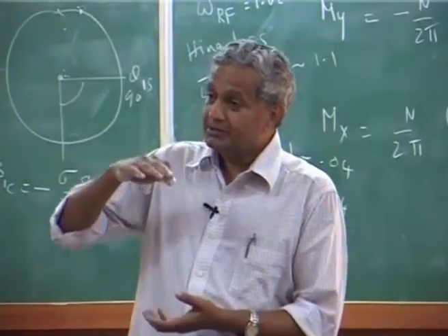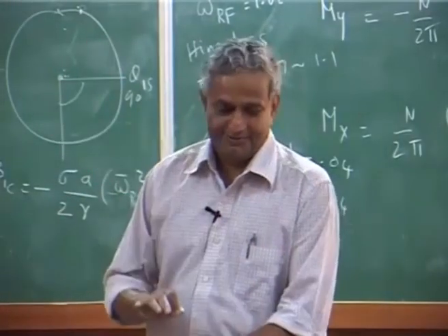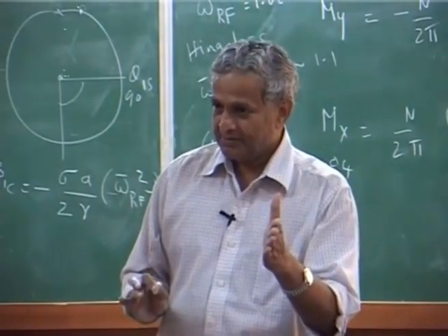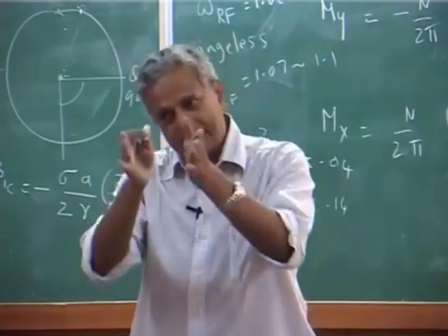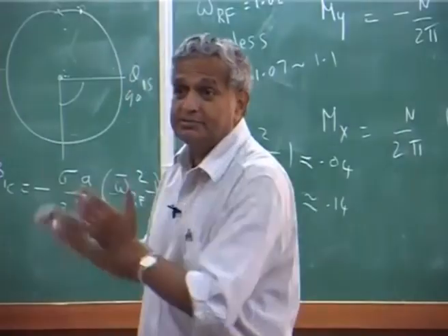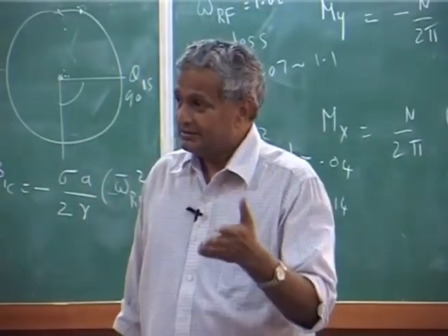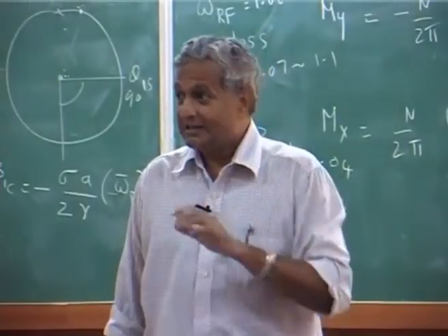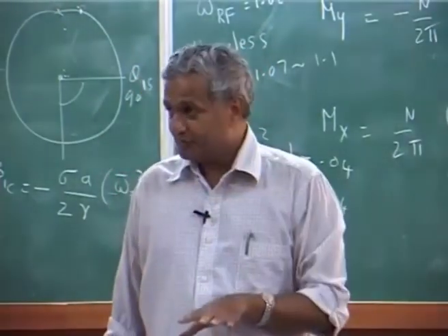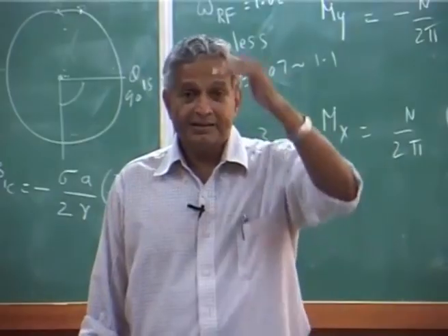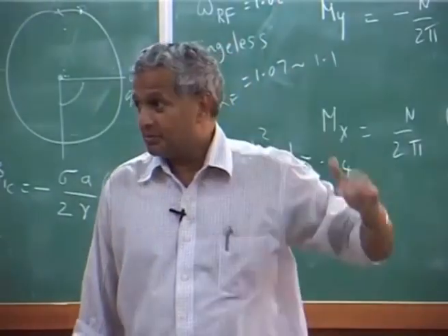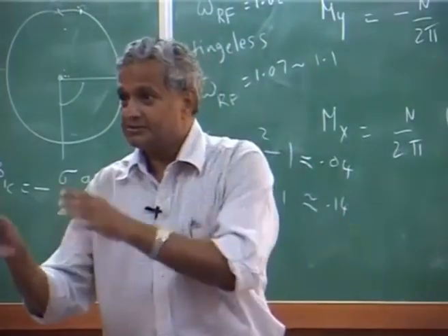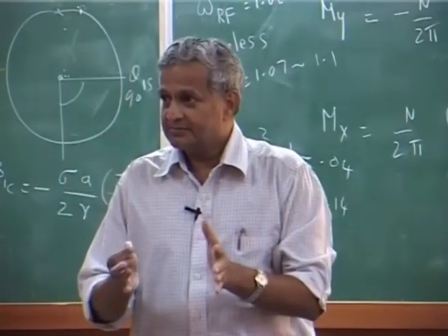That means coupled blade fuselage dynamics. You follow? And that has its own set of problems, like you have flap motion coupling with the fuselage, lead lag motion coupling with the fuselage. Each one has its own stability problems, okay. And then flight dynamics is rotor and the fuselage.